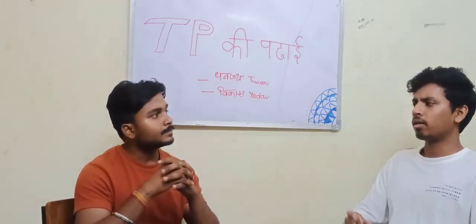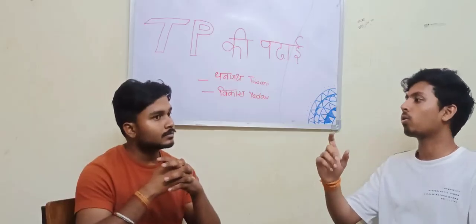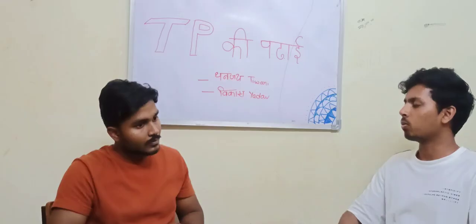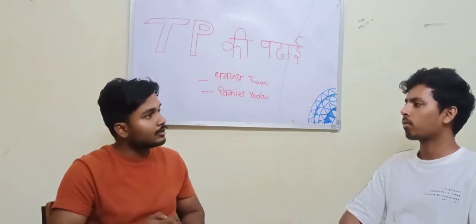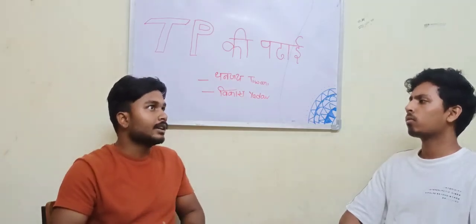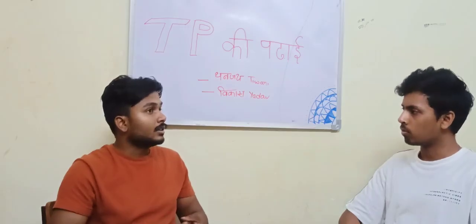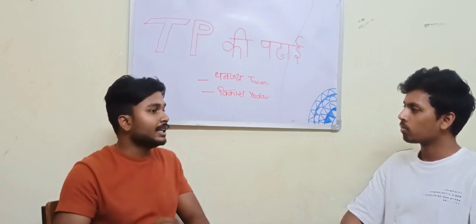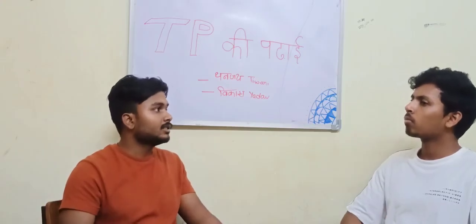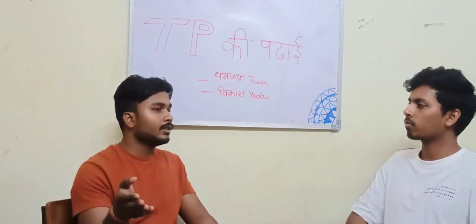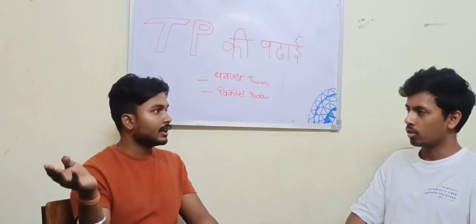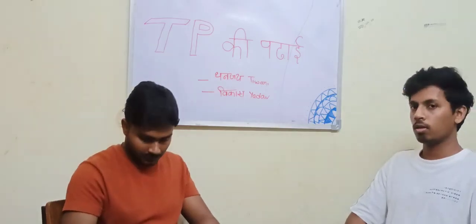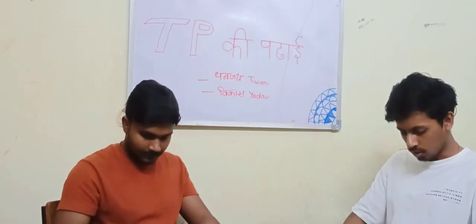But many times the temperature difference is not given, or it is not constant, it is varying, and the area is not given. So in that case, what can we do? We have studied in transport phenomena that there are various empirical relations like Prandtl number, Schmidt number, and some analogies like Chilton-Colburn analogy. From those dimensionless numbers, we can easily calculate the required parameters like h, k, Cp and everything. So use the values of these numbers, get the coefficient and put it in the formula. You can easily get the heat transfer coefficient. Okay, so this is a very important thing to note down for our students and viewers.